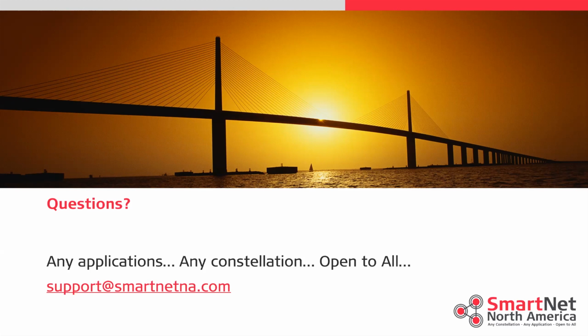If new stations are added into BC, we would project them back to 97 or 2002, because there's already inherent error in 97 and 2002 because of how those reference frames were originally realized anyway. So there's nothing that we can do that would fix for that in a velocity model. So if we bring in new stations, we can get back to 97 or 2002 in BC because there's already inherent error there that just will be there.